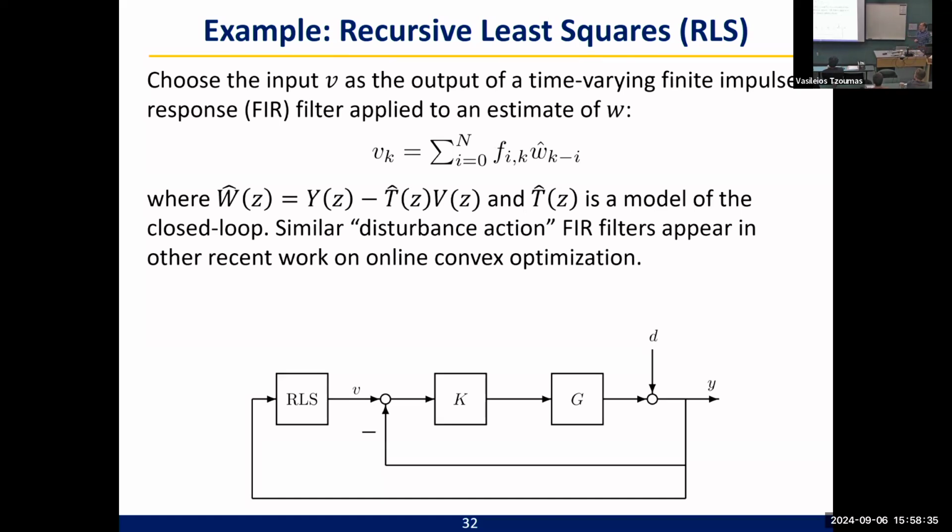This is what distinguishes this type of application from things like noise canceling headphones. We need to first estimate what we think the disturbance is. We don't get to directly measure that. That may seem like a minor point, but it's not, because embedded in here, this feedback is inside of here: we take Y, we estimate W, then there's some FIR filter. There's this extra feedback loop, and adding that extra feedback loop can actually cause things to go unstable. That doesn't typically happen in noise canceling headphones. There you're measuring the disturbance and just directly feeding it in here. There's an open loop path.